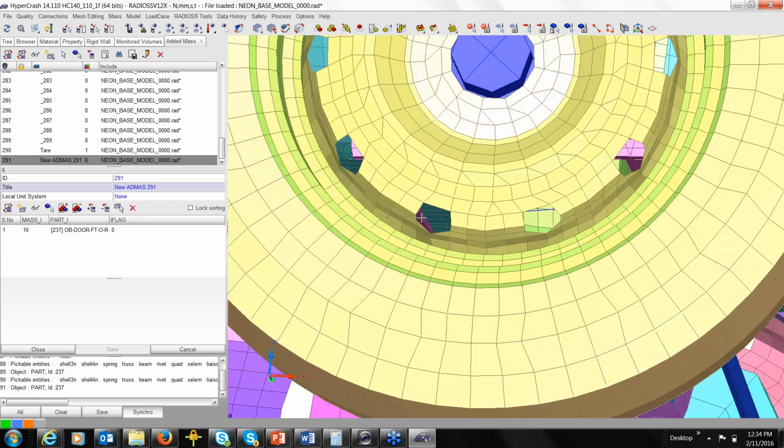A hole is maybe 2 millimeter diameter, okay? And you want to represent that hole of 2 millimeter diameter. So what you have to do, you need to mesh around those 2 millimeter diameter. That will dictate your smaller size of the element for this scenario. In the other area where you don't have the hole, you have a nice geometry, your mesh size could be larger.